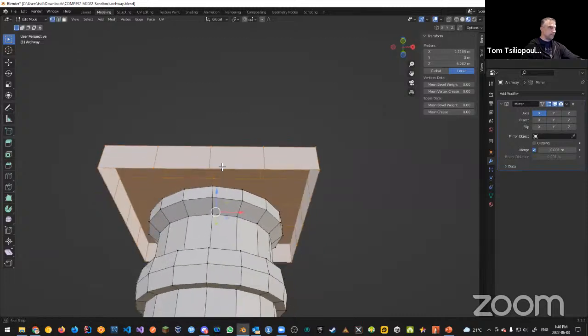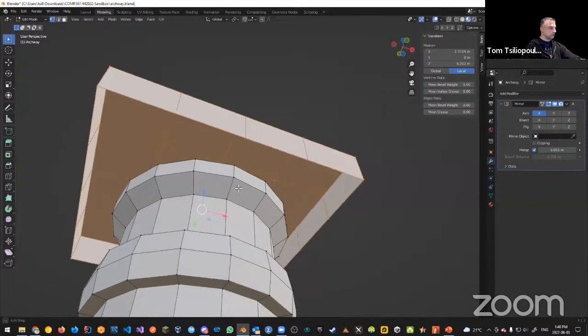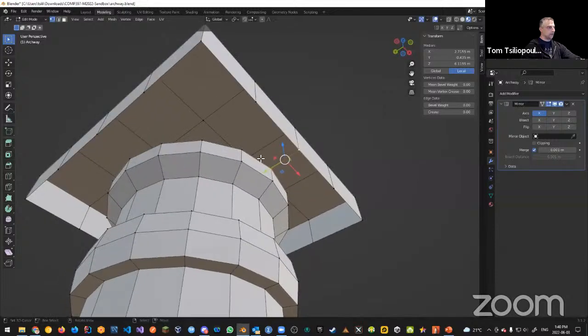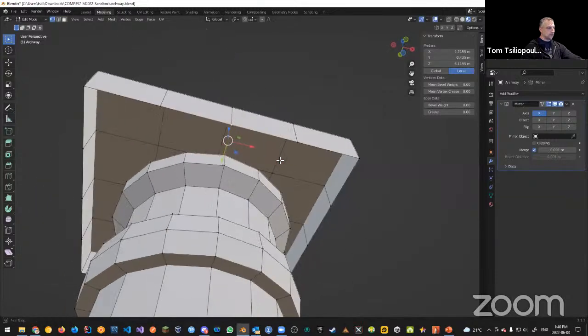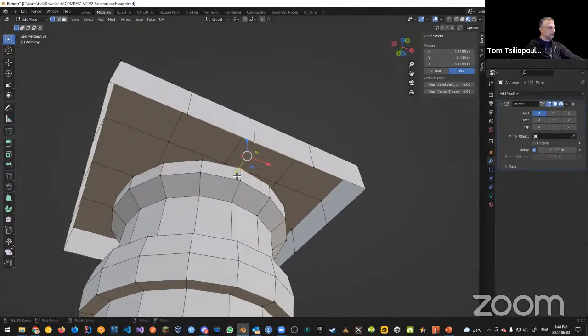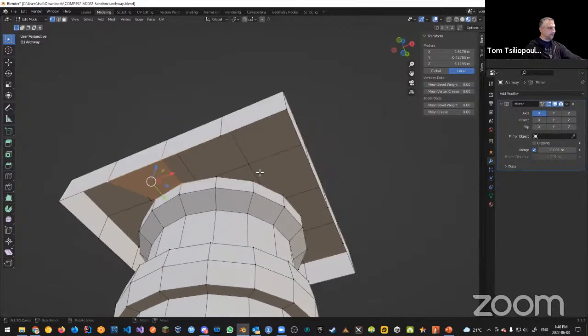So again, one thing we want to make sure that we don't do is select the wrong vertex. Okay, so again, what we want to do is deselect all and then go vertex to vertex. And then we want to press F for the actual face. And let's try doing it so that instead of doing F multiple times, let's undo that. We can just do all those vertices all at once. So this one, this one, this one, and this one, and then press F, and we create a face immediately.